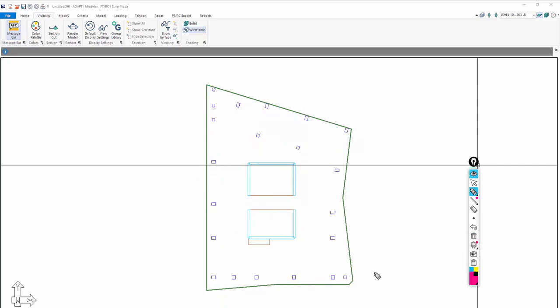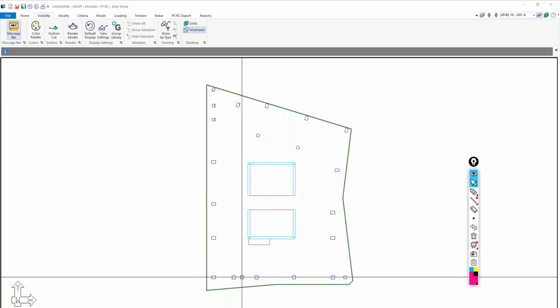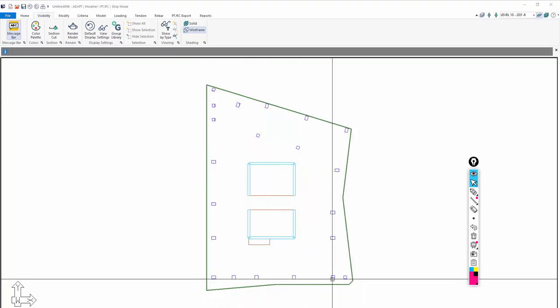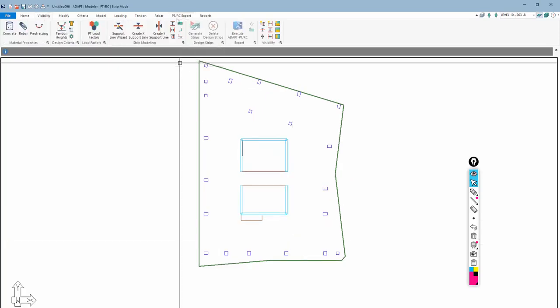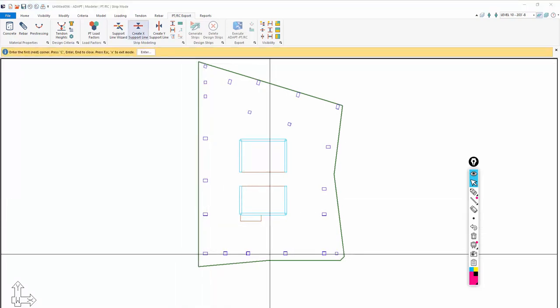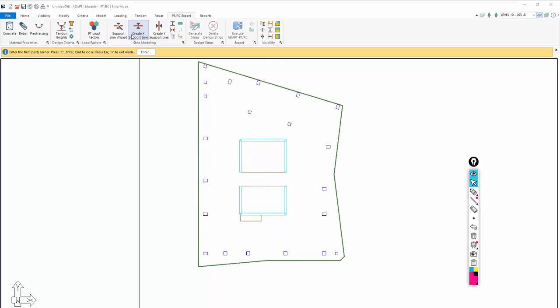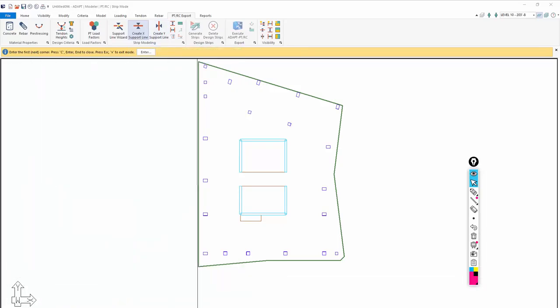We're going to actually just go and in reality, we're going to create one support line here. We're going to show an example on one frame line here in the X direction. So we're going to go to PTRC Export. I'll be using the strip modeling tools. I'm going to create a strip in the X direction. This really could be direction 1, direction 2, direction A, B. It doesn't necessarily have to be aligned with these global coordinates.